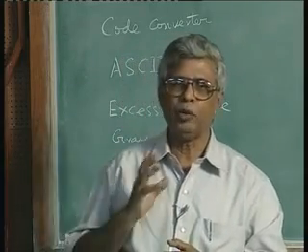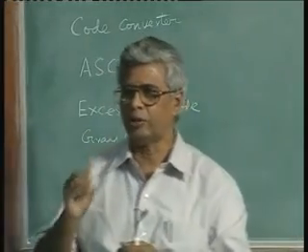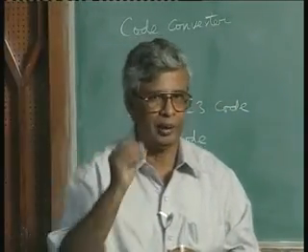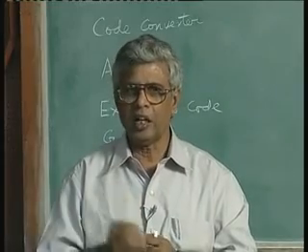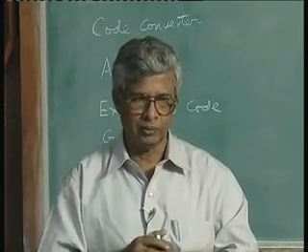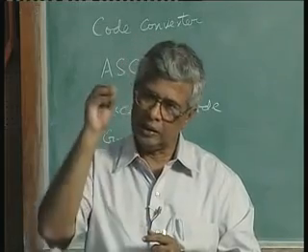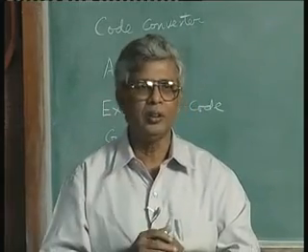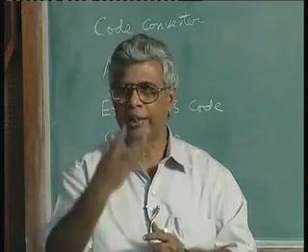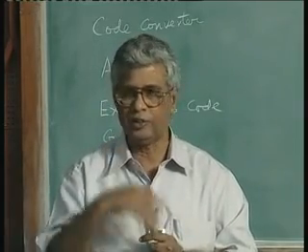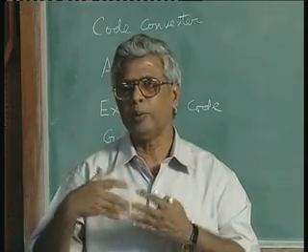Don't say that when using a computer you always have to follow the natural binary sequence. It's not necessary to use a natural binary sequence for inputting numbers into a computer or any digital hardware. Into any digital hardware you can have a coded number, perform the operation in the code, get the result in the converted code and reconvert it back to the binary number with which we are familiar. So that is why I thought I will give you some examples of code conversion.